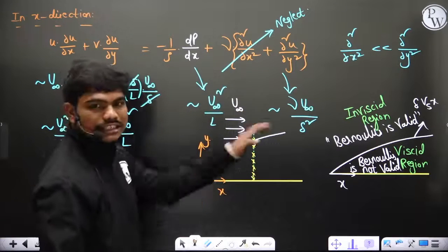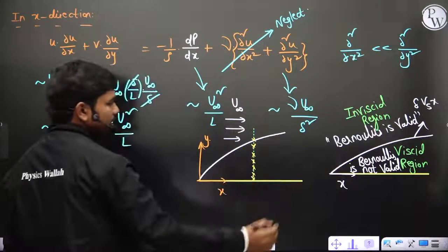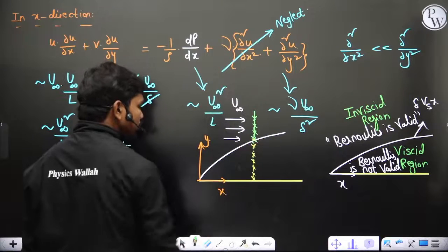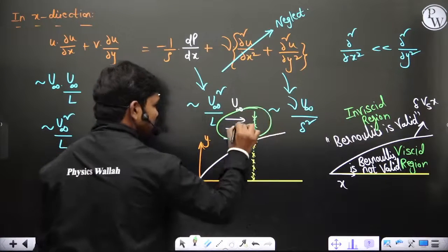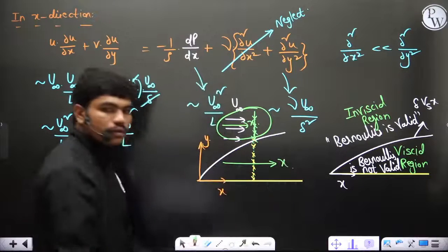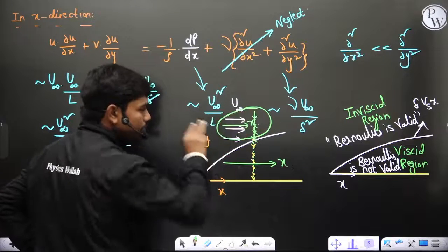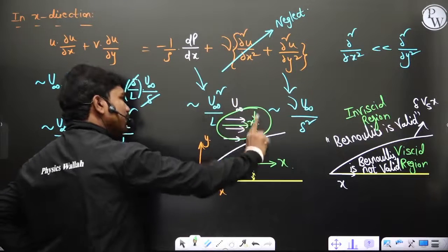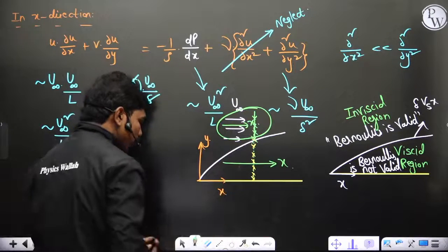This x is basically the stream direction. So if x is stream direction, clearly you can see from your Bernoulli's equations, this pressure remains same here. That means overall there is no pressure gradient in the y direction. That means whatever is the pressure variation here in terms of x, same pressure gradient will also get imposed in this boundary layer. Yes or no? I'm repeating this statement, see carefully. You know outside this the flow is one dimensional, it's u infinity, along the stream direction. Then perpendicular to the stream direction, since there is no velocity, pressure remains constant along this. And also, at this point there should definitely be continuity.